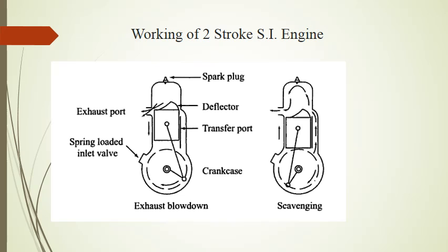In a four-stroke engine, the operations are performed by the engine piston during the suction and exhaust stroke, respectively. In a two-stroke engine, suction is accomplished by air compressed in crankcase or by a blower. The induction of compressed air removes the products of combustion through exhaust ports. Therefore, no piston strokes are required for suction and exhaust operations. Only two piston strokes are required to complete the cycle, one for compressing the fresh charge and the other for expansion or power stroke.